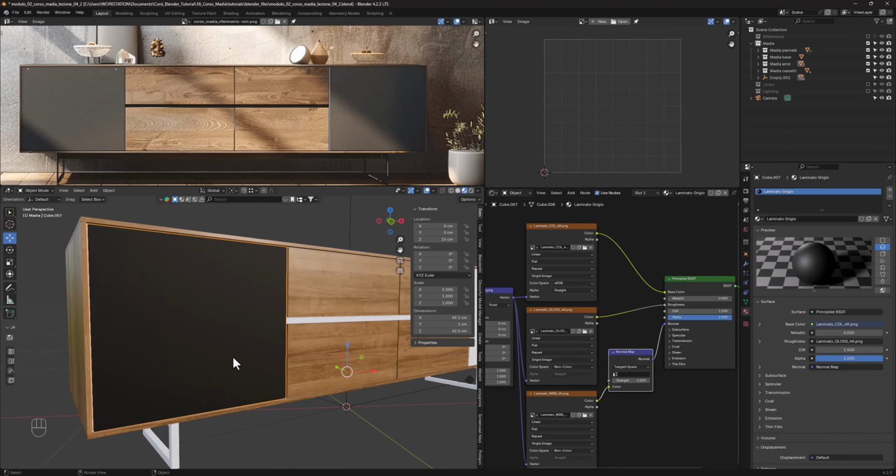At this point, we only need a small degree of glossiness and reflection. Press Shift+A and type Invert. Select Invert Color and place the node in the connection between the Glossiness node and the corresponding channel of the Principled node.